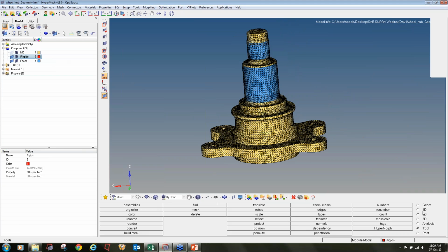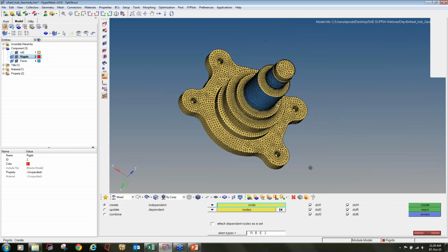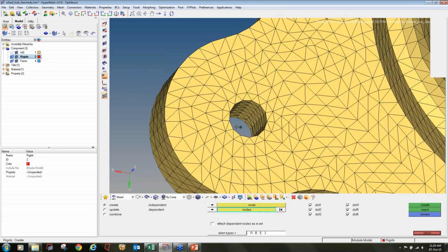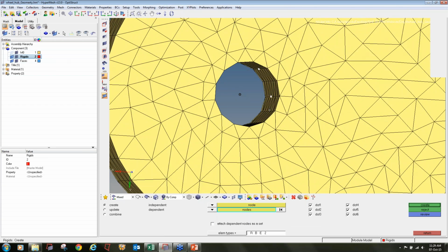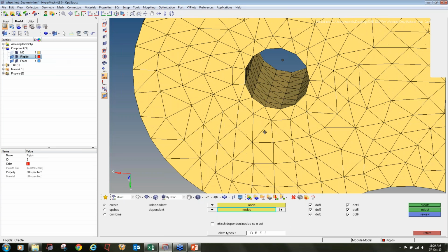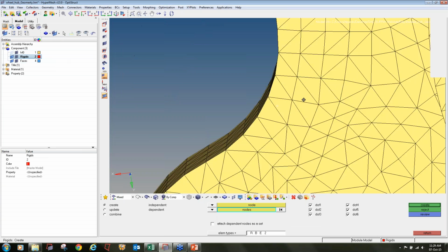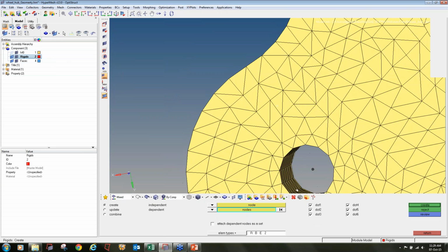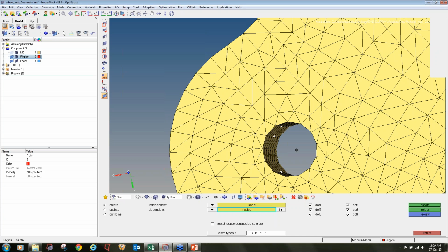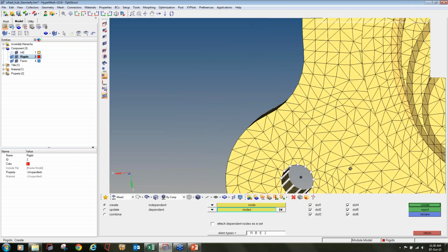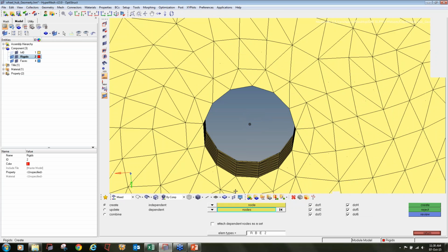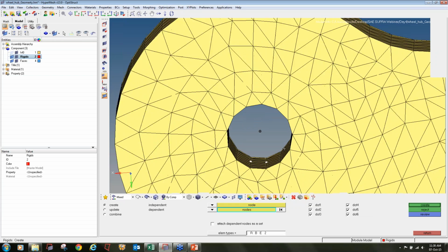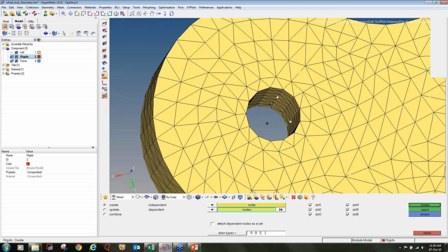So I will go to 1D page rigids, select this node and select the nodes arbitrary at the inner surfaces. Say nodes by face. Click on create. Similarly, this node, some arbitrary nodes at the inner surface.